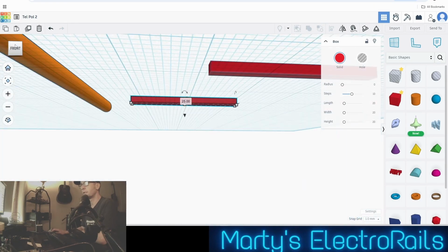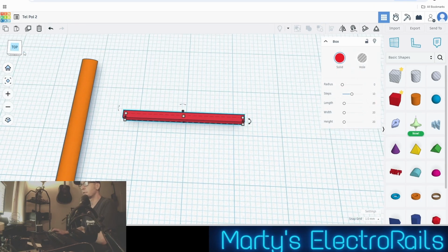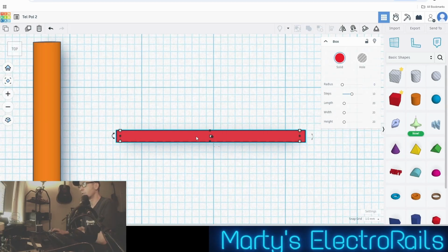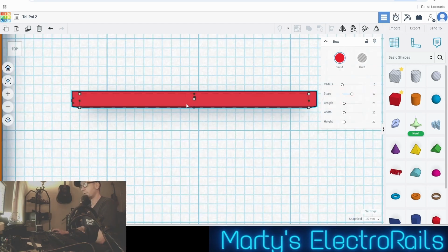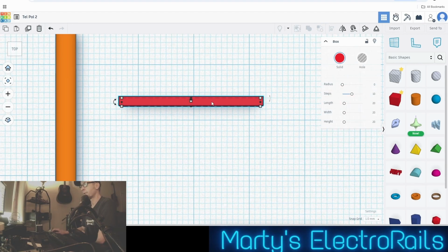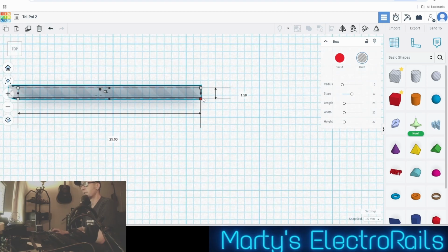You can rotate that and click front. It just clicks to a plan view of that shape. Another thing we can do, we can make that hollow so we can actually see where these points lie within the grid. I want to move that centre point to there.